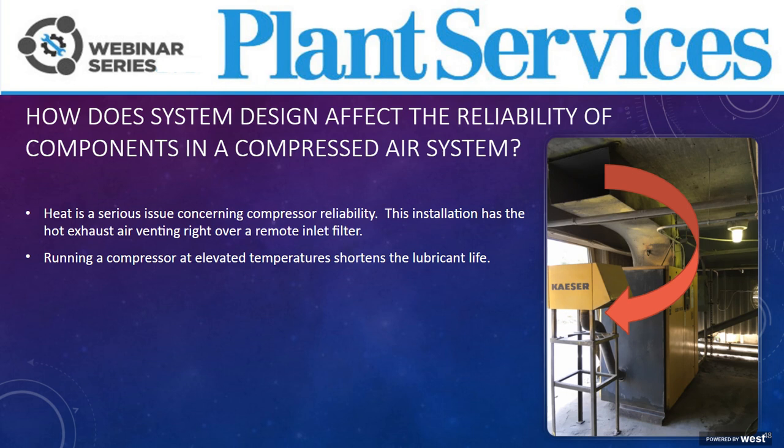Overheating is a significant issue with rotary screw compressors, or can be. And in this case, the customer did a wise thing by buying a remote mounted intake filter, but he mounted the intake filter right under the exhaust duct for the compressor and was recirculating the heat.